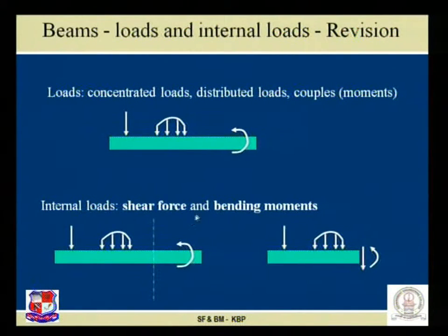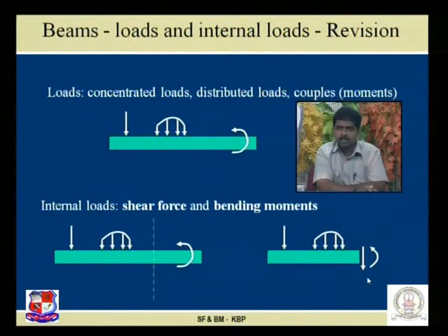Now let us divide this given beam into two parts, left part and right part, and let us study one of the parts, the left section over here. If we refer to this left section, these internal quantities which were developed in terms of force as well as moment are referred to as shear force and bending moment.